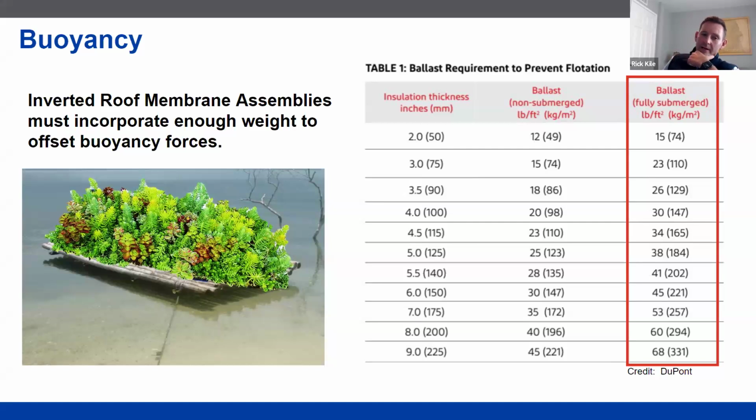If we think about our R-value requirement being 30, that's 6 inches of traditional XPS, and it's 45 pounds. So there's a significant ballast weight, and that does end up becoming a significant consideration in a condition where we might be super saturated or fully submerged over 24 to 48 hours. Oh, 100%, as we get these big storms coming in, right?